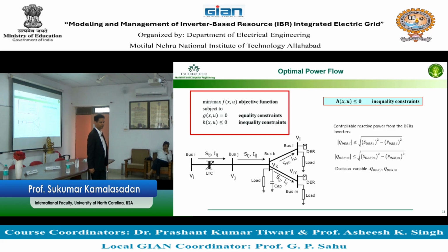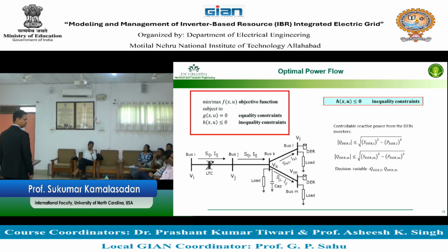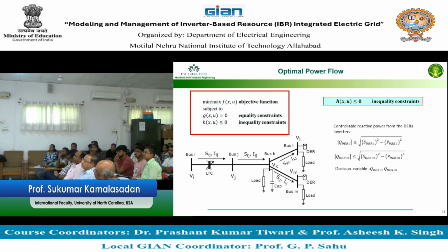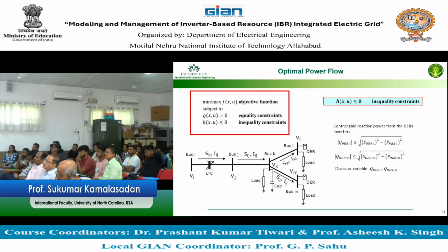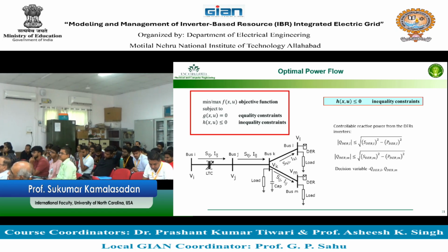And that's sacrificing the real power. So that is a trade-off. So what you have to find out is, for example, in some places you need to improve the voltage, and you are operating at maximum power point tracking, like you said. You have a curtailment problem, you have to cut it, or if you are not cutting it, you have to improve the voltage so that you can push the power through.